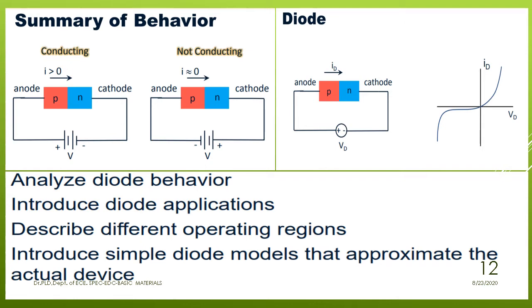Already I told you the reason: the number of charge carriers per cubic centimeter in germanium is large. By applying a minimum voltage, it allows current to pass through it. That's why the cut-in voltage of germanium is lesser than silicon.